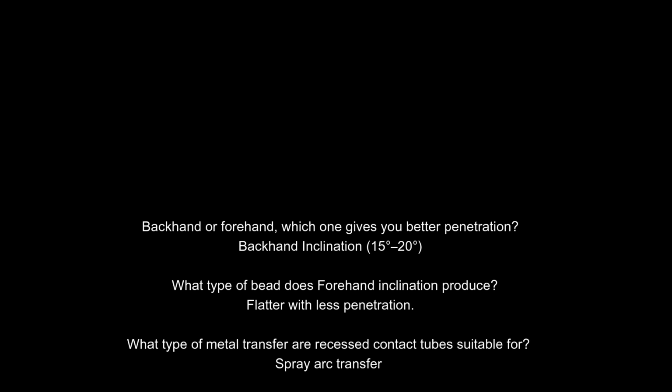Spray arc transfer. Contact tips must be centered to ensure what? Equal gas distribution to the weld puddle. What mode of metal transfer are recessed contact tips meant for?